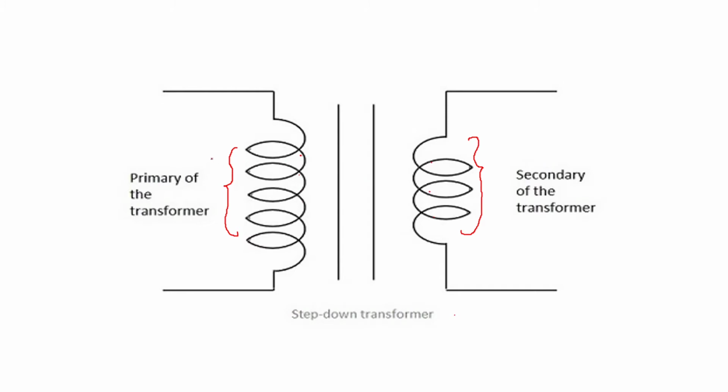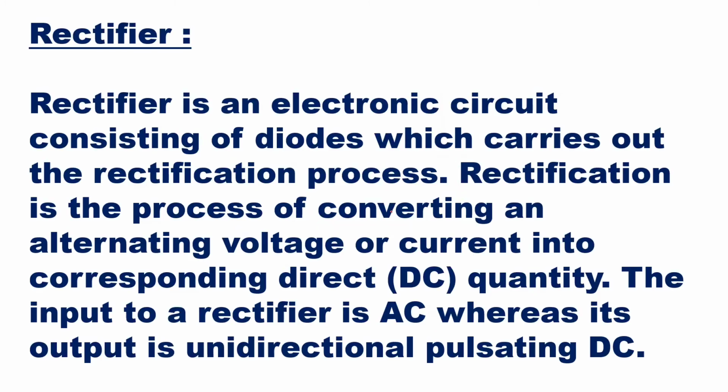Okay, so a bigger voltage, say around 230 volt, can be converted into a lesser voltage, say for example 5 volt. And this is your magnetic core, where electromagnetic induction takes place. That is, magnetic lines of flux will get cut by both the coils, and that is how the power will be transferred from primary to secondary. Clear? So this is what a transformer is.